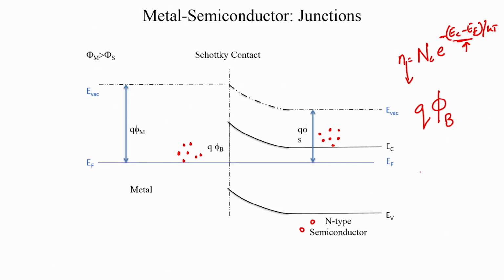What I mean by that is, let us say you have a metal and you have a Fermi level, and you start increasing the voltage of this metal. What would happen is that the Fermi level will start moving downward. So, if you see two energy levels in an energy band diagram, then the level that is lower has a higher electrical potential. That is just the convention. It is drawn thinking of the electron as rolling downhill. So, the electrons would like to roll downhill towards the higher potential, and the holes would like to roll uphill towards the lower potential.